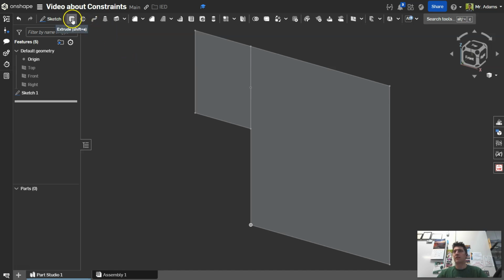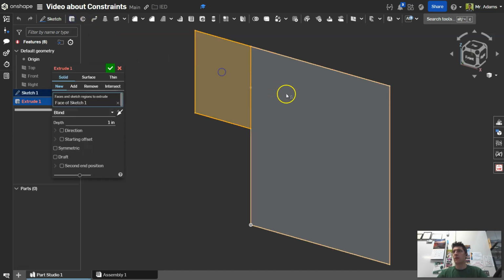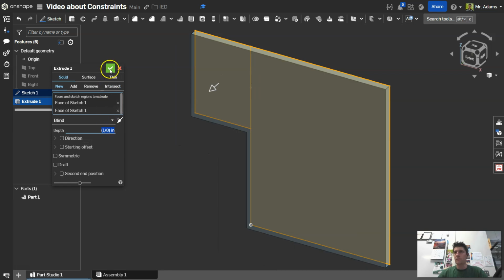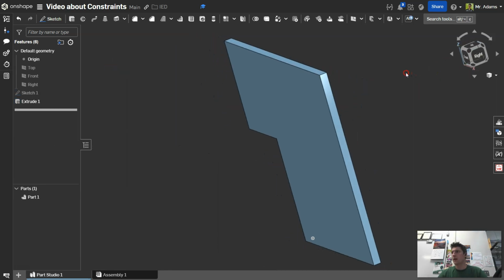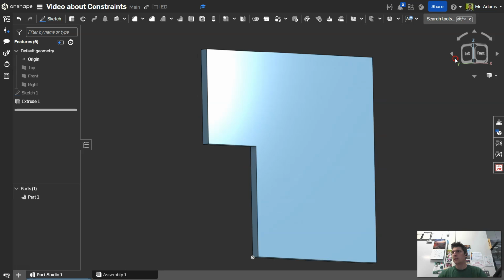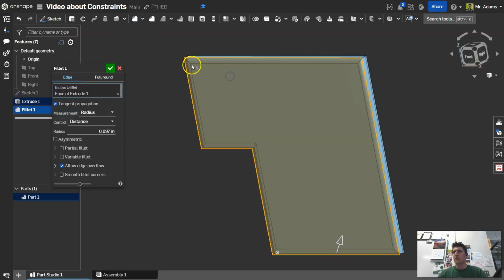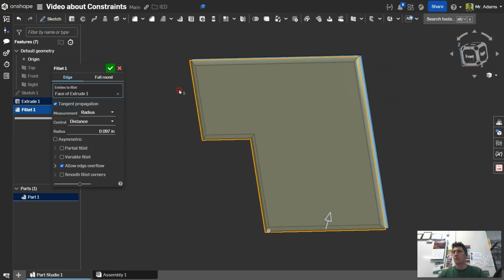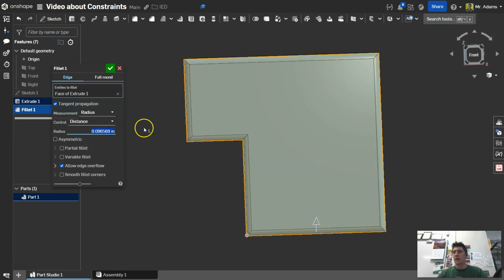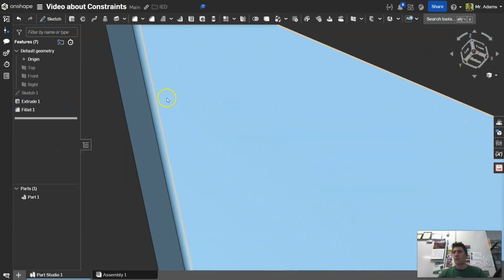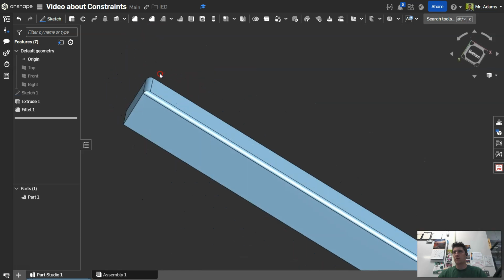So, for this basic object, just as we've done before, I could extrude this thing. Let's say that I want it to be 1/8 of an inch. So there's my 3-dimensional object. It's just a really thin block, essentially. And we've got a lot of tools that we've used to modify shapes. So on this end, I will add a fillet, and let's make that fillet 1/64, just to keep it really small. But when I zoom in, you can see that that corner is rounded off.